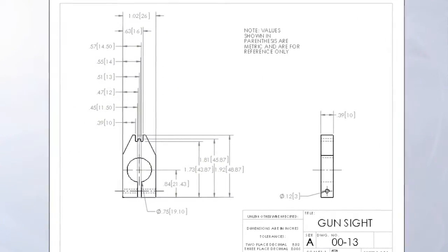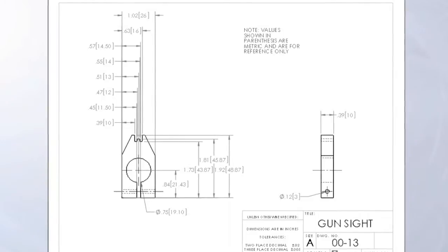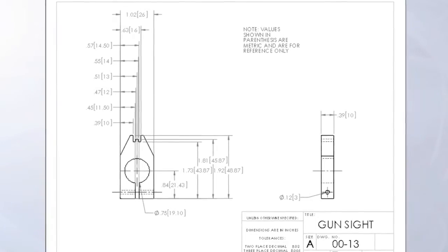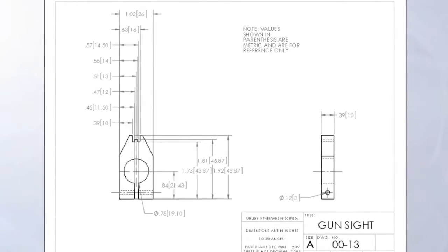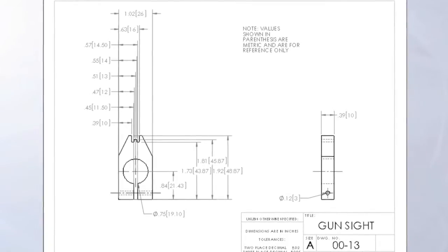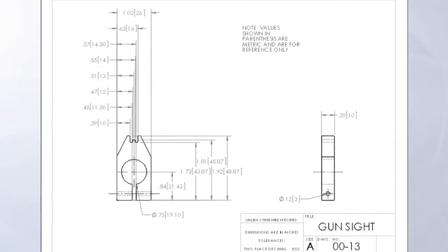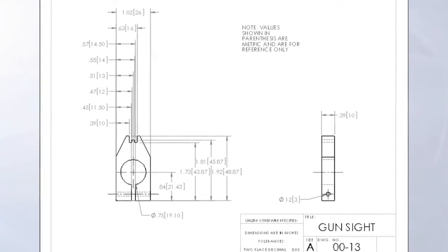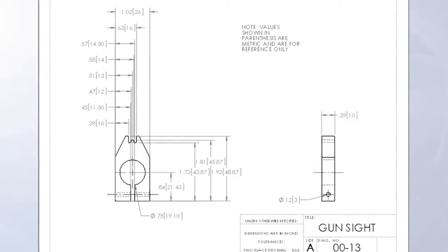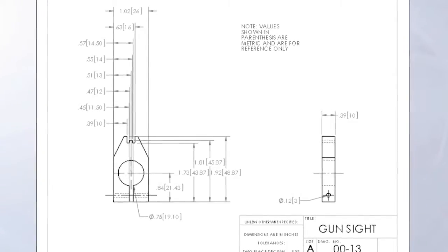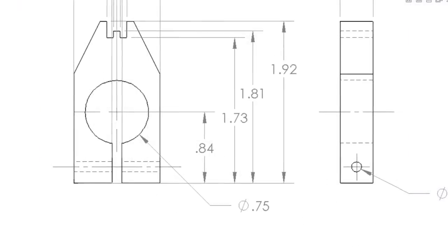The placement of dimensions is important in terms of readability as well as print clarity. A blueprint should be dimensioned so that the print is not cluttered with excess measurements. The correct application for dimensioning requires that the size and location of features be dimensioned in height, width, and depth, along with the location or position of the feature.